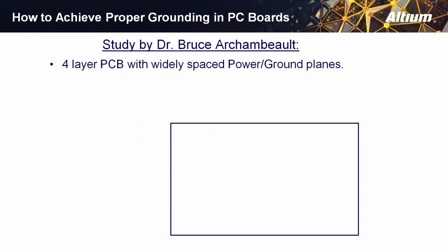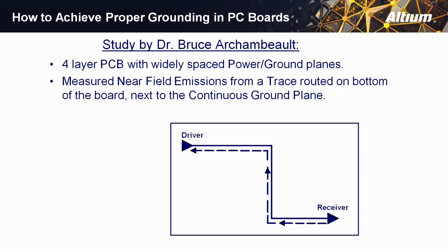What if it's something like a 4-layer board? Dr. Bruce Archambault, who spent a large portion of his career as a senior fellow at IBM in the Carolinas in the United States, ran a study one time where he tried this. He tested this on a 4-layer board. Remember, the dielectric on a 4-layer board is very thick between layers 2 and 3. So he put ground on 2 and power on 3. And he set up a signal and a receiver on layer 1, and he fired it up, driving a signal from the IC on the left to the IC on the right, referencing a solid ground plane.